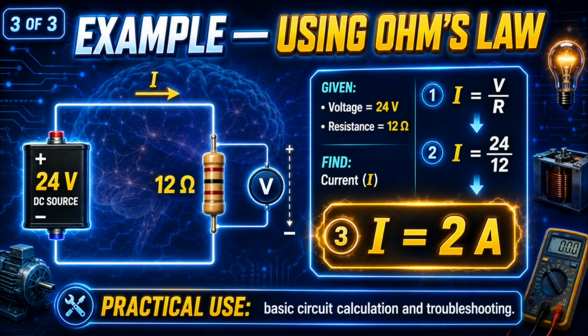But here is something important to remember. When using Ohm's law, always pay attention to whether the resistance is given in ohms or kilo ohms, because that affects the unit of the current answer. Let's look at that more clearly in the next slide.